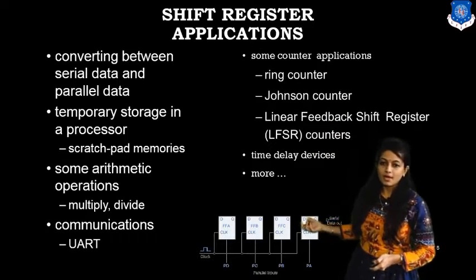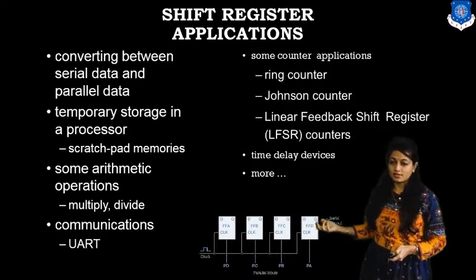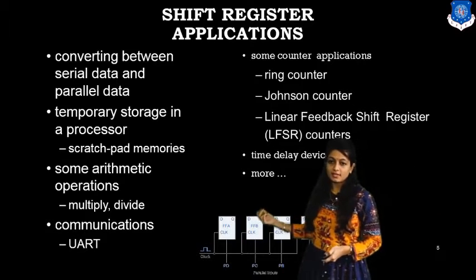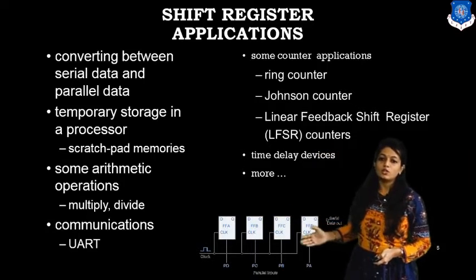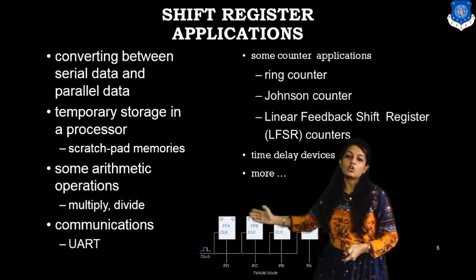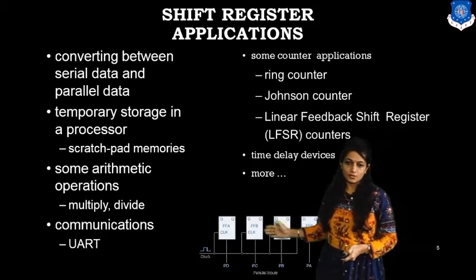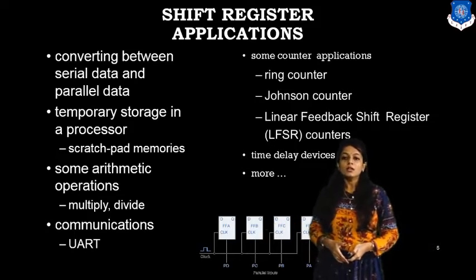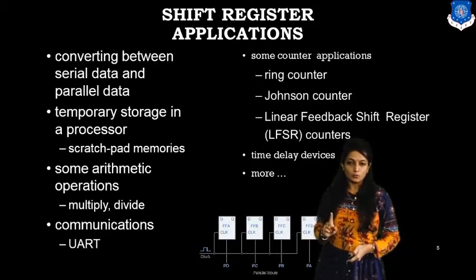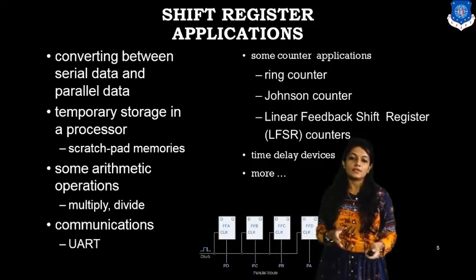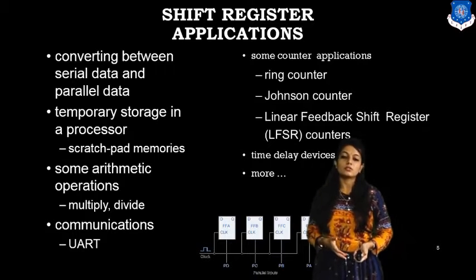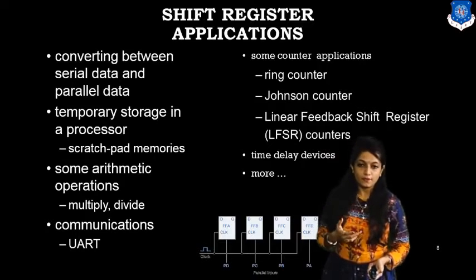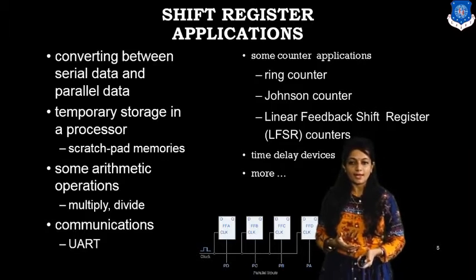This is an example of how it looks. The shift register consists of 4 flip-flops. You can see that we are going to use D flip-flops. The 4 flip-flops are synchronized at the same time, and the clock pulse is given to all flip-flops. It has only a single output when we shift the data serially, and it has multiple outputs based on the number of flip-flops when we transfer the data in parallel.